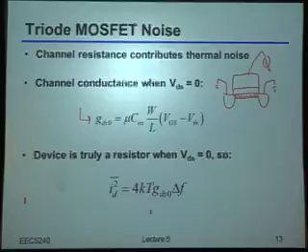So again, this GDS naught parameter here is really just capturing the resistance of the MOSFET in this triode region of operation. So now, why does life all of a sudden get a lot more fun when you're in saturation? Which, for better or for worse, is going to be the region you're probably going to mostly care about, given that this is an analog class. Channel pinch-off. Okay, so you're right, but what do you mean by that? How does that complicate this picture?